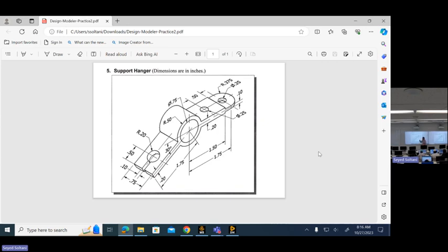And I want to make this symmetric around the x-axis so that later, if I want to slice it into a quarter model or a half model, it would be easier. Even though I'm not going to use the x-axis to slice this, it would be easier to add some constraints to the geometry so that later it would be easy to manipulate. All right, so 1.5.